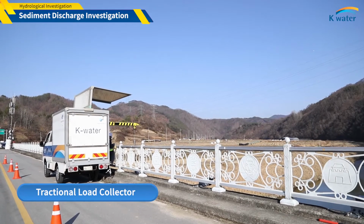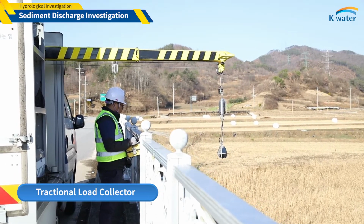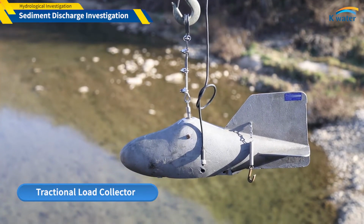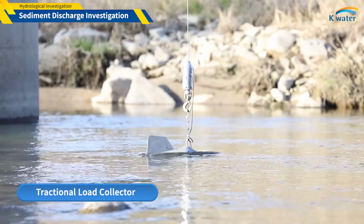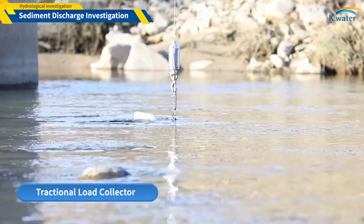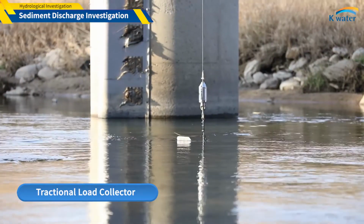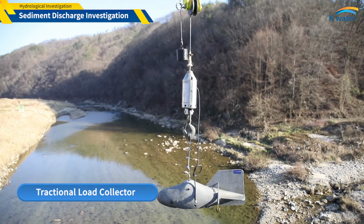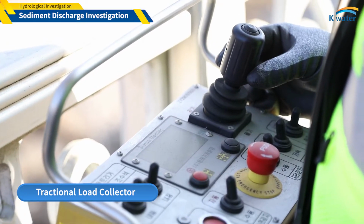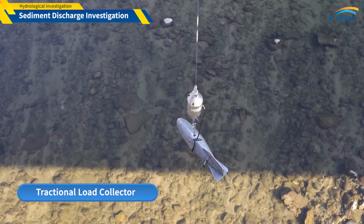The tractional load collector collects soil from the bottom by lowering it on the riverbed. The inside of the tractional load collector has a ladle-type bucket, and when the collector reaches the bottom, the bucket closes and the tractional load is collected. When collecting the tractional load, care should be taken not to disturb the riverbed, and if possible, use a vehicle or a hoist at the location where the flow rate is measured.